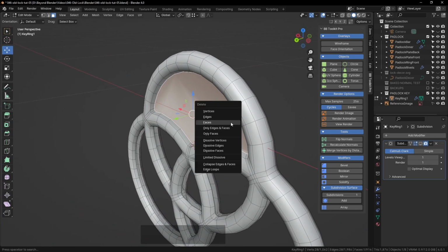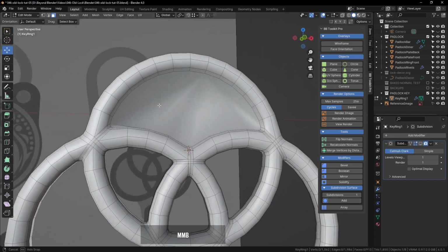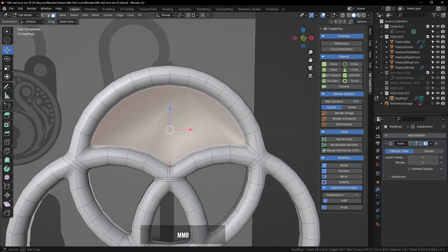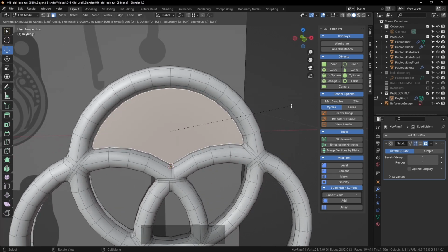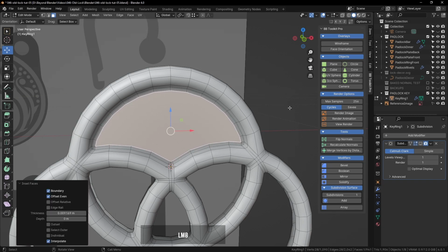And just think about that. Let's delete the back one. We don't need to work on both of them. We just need the one for now. So I'm going to do a selection on the one n-gon there. Press the I key and bring it in just so far. Not too far in, so that it collapses on itself.